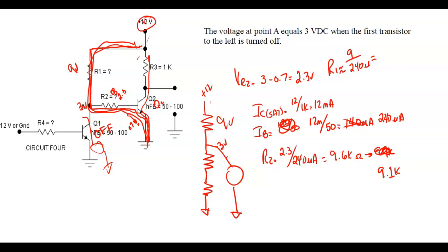So what do we get for R1? 35.6K. Yeah, 33K. Okay, so that's on the collector side of it, R3, right? Either one, R1 or R3, are both on the collector side of it, correct? Well, this is on the collector side, or this is on Q2, over here on collector, we round it up.